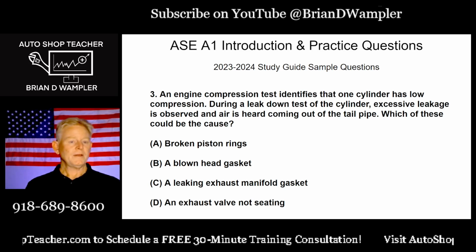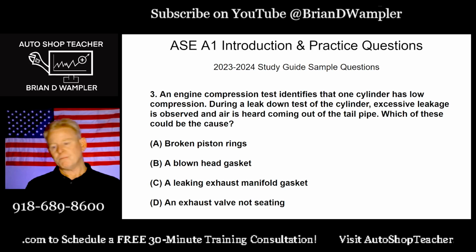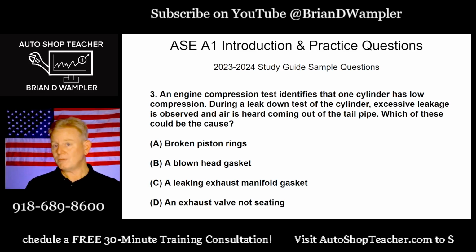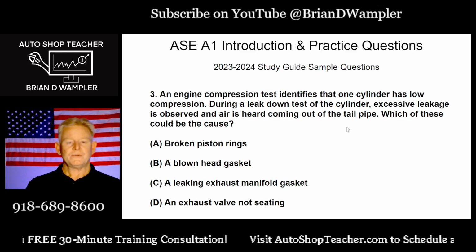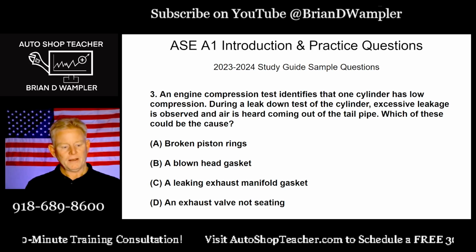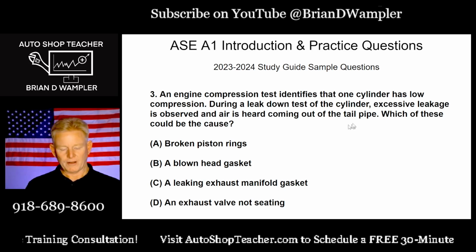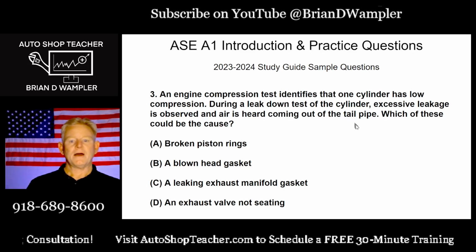Or maybe, based on the mileage and what we find from the leak down test, it's in their best interest that we jump all the way to a short block or a long block. Okay? So we do these sorts of tests not just to entertain ourselves, but so that we can make informed, professional recommendations to our clients, right? So air is heard coming out of the tailpipe.